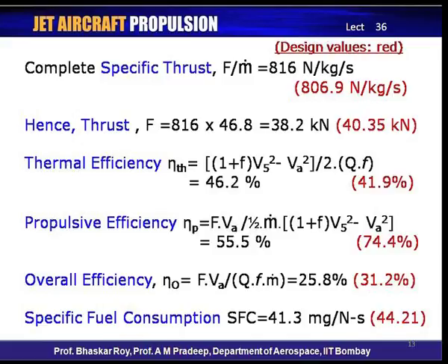Next, we can find the propulsive efficiency, for which we use the definition that we introduced earlier in this lecture series, and that is the actual thrust work done by the engine, F into V_a, compared to the energy that is available with the gas, which is the exhaust energy minus the entry energy, which we used in the earlier definition in the numerator.